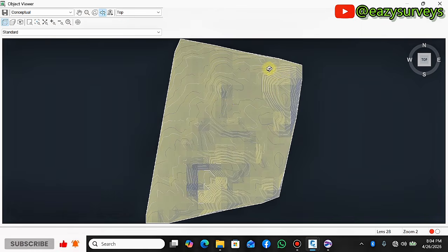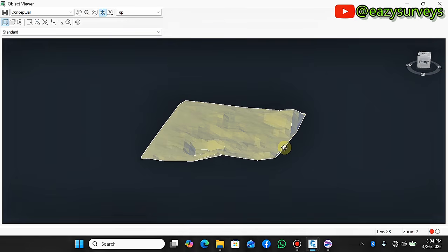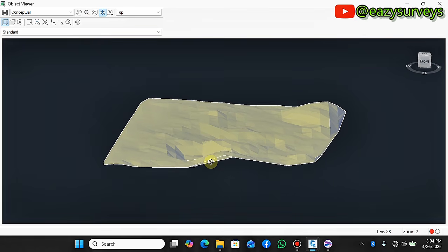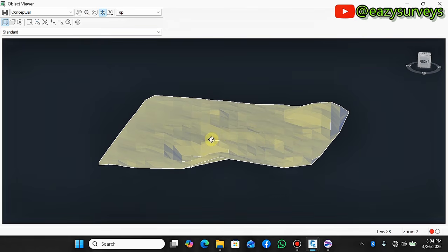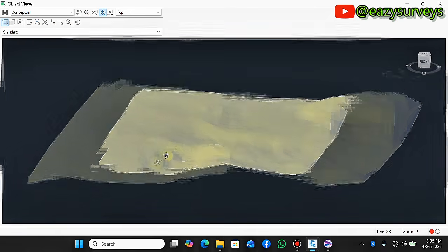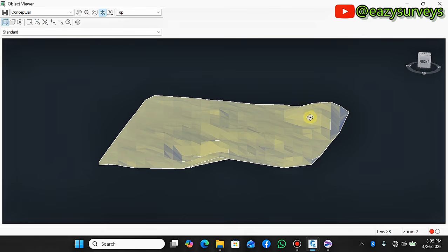So there is a particular material field up here, that is a sand, right? So my client wants me to compute the volume of the material. There's a sand heap within this section so that he can know if it meets what he has actually bought from the buyer. For as many as possible who do not know the application of topographic surveys, this is one of the applications. You can use it to quantify materials, to know what you are buying, to sample some area that is deep, to know the quantity of what you want to buy.